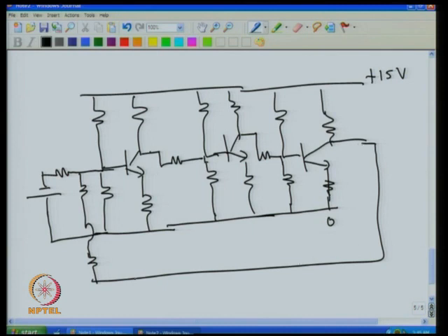Eventually what will happen is, if I stabilize the loop by putting capacitors and so on, you will see this fellow, which is getting contribution from this as well as from this, the 2 contributors, one from the feedback voltage, another from the applied voltage, trying to go close to 0. That is what happens, because when this is just about 0.6 or so, it conducts, and then it gets some voltage, so that this also gets some amplified voltage that comes from here.